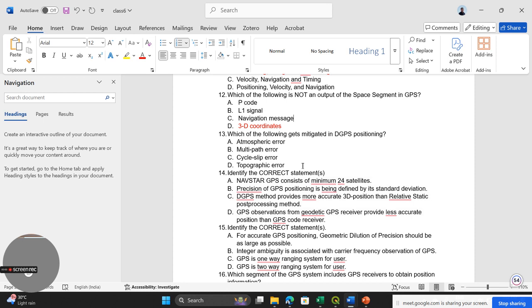rover. So we have GPS, two stations, base station and rover station. Yes. So what we do is, first of all, we know the coordinates of the base station, and then after we get the same data for the same station where we know the actual coordinates. So we find out the error in delta x, delta y, and delta z, and that error we will correct in every other observation. So now we are correcting in other observations. So when can we correct? If the error is same for both the